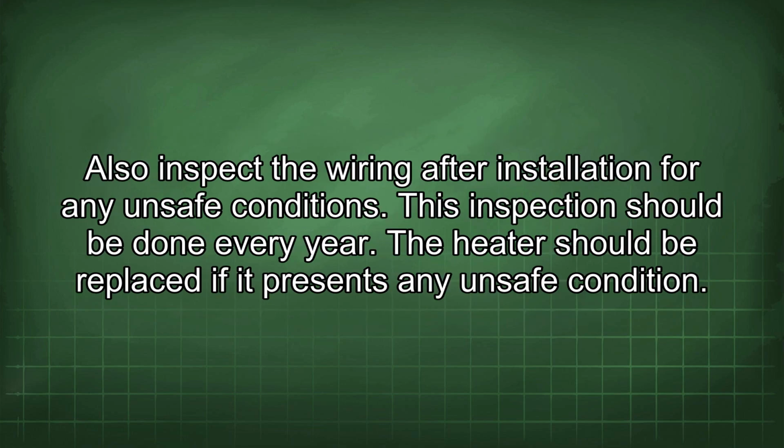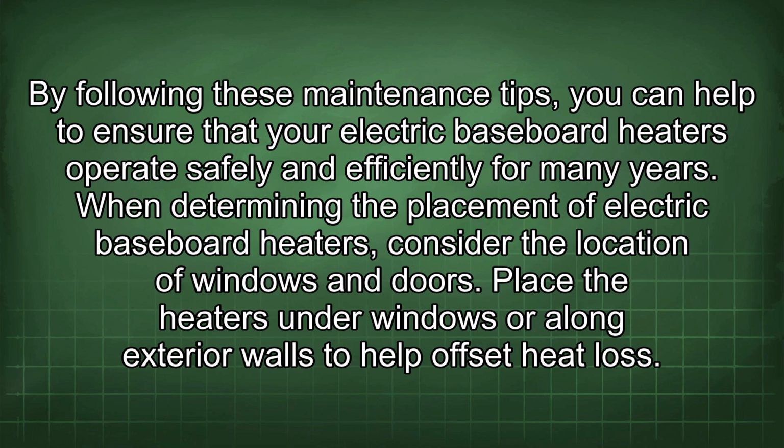Also inspect the wiring after installation for any unsafe conditions. This inspection should be done every year. The heater should be replaced if it presents any unsafe condition. By following these maintenance tips, you can help to ensure that your electric baseboard heaters operate safely and efficiently for many years.